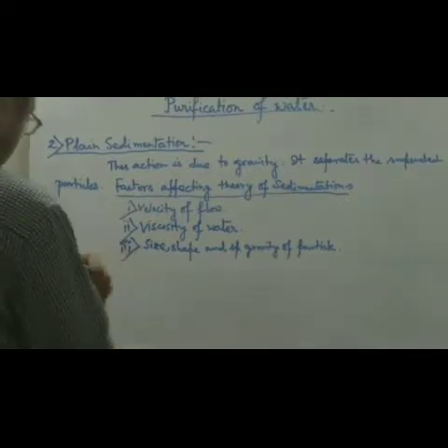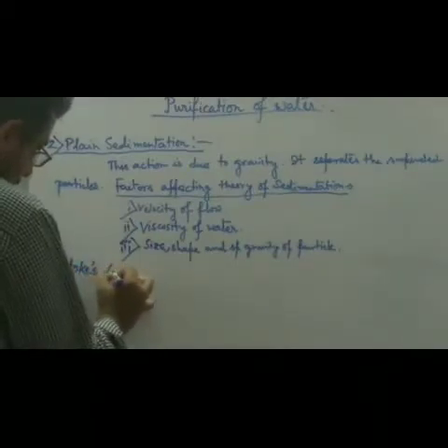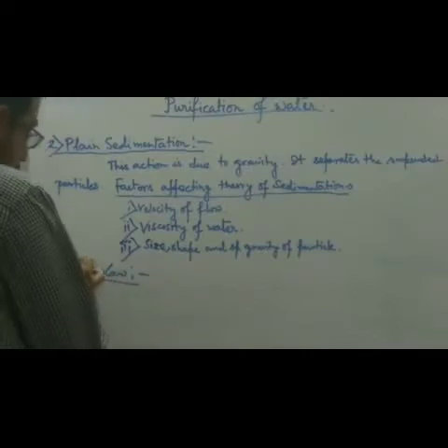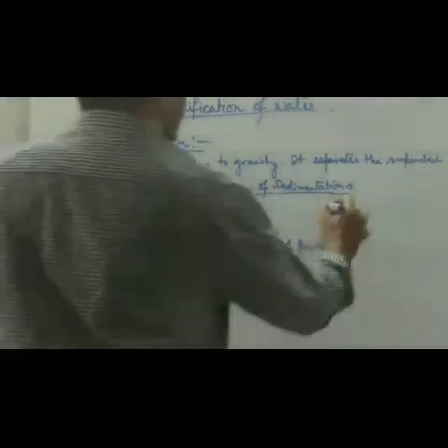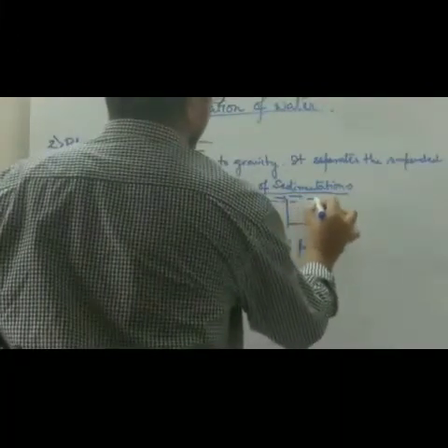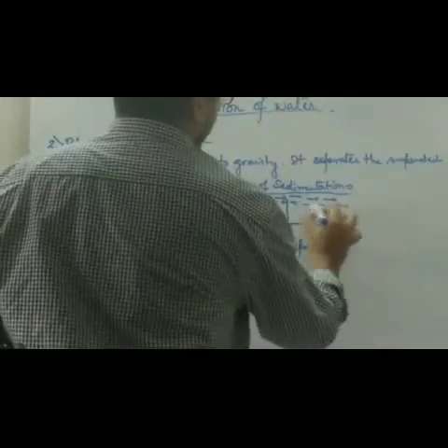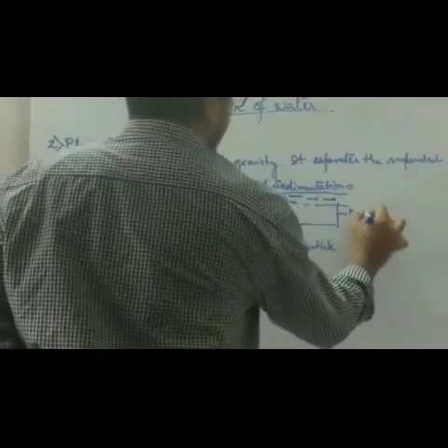So please write down, that is Stokes law. It is very much important because the Stokes law describes the settling velocity of the particles. So suppose this is the sedimentation tank, and here is the horizontal flow of water, and this is inlet and this is outlet.